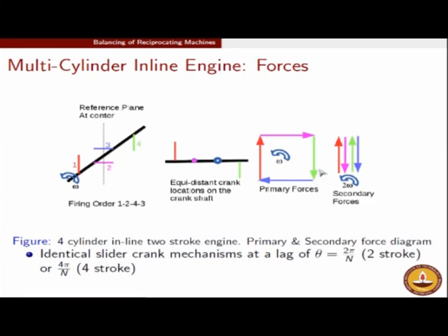But even for the sake of completion, if we wish to draw all the forces, as I said, the way to determine these shaking forces is to first consider the rotating unbalances and then take the x component of it. So at this stage we are not worried about taking the x component. We will just find the total rotating unbalance due to this group of forces.